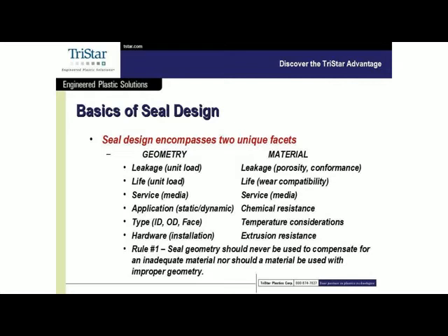And the service type, what's the media? Is it hydraulic fluid? Is it water? Is it gas? Is it oil? Is it inert gases like oxygen or nitrogen? Those will have a critical factor when it comes to the geometry design. The application, static or dynamic. You can get away with a lot of things statically without using filled materials. Virgin Teflon does very well in static conditions, but it depends on the pressures and what else is going on in the environment.